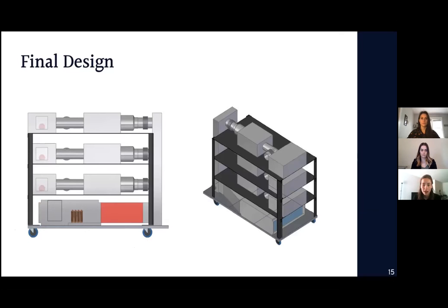After the fan coil, an electric duct heater is installed in the ductwork. This is discussed a little bit later in the laboratory exercises section. After that, the air is pushed into the 3 systems. Each shelf has a manual balancing damper for manual control of the system.